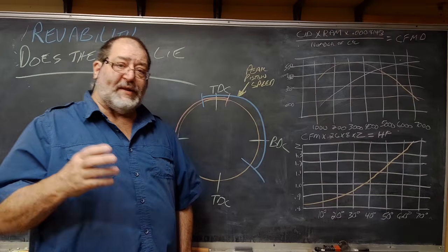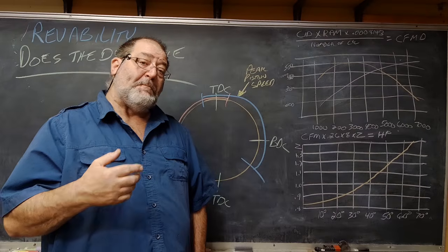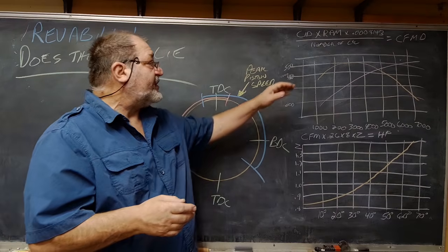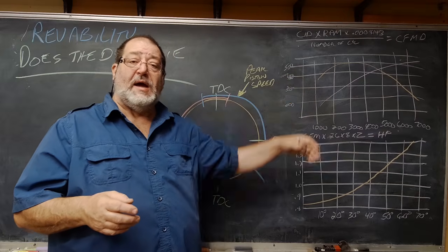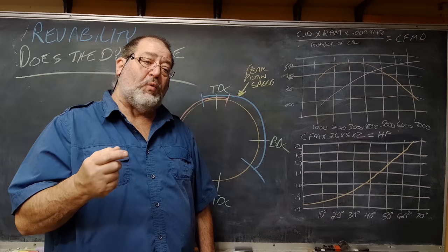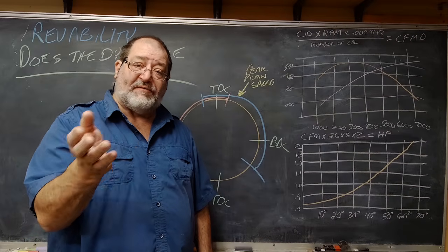Now, we're really good about putting big heads on motors, sometimes bigger than what the engine should actually have, and costing you low end power. And certainly if the engine is struggling, with airspeed, it will not rev as well.